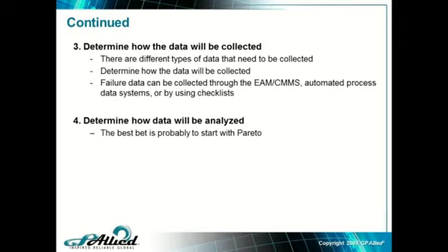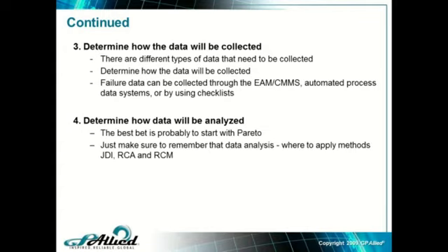And I say the best bet is probably to start with a Pareto analysis. That's the easiest way to start. And just make sure to remember the data analysis, where to apply it, okay? You can just do it, JDI, I call that a JEDI, just do it, you see the problem, solve it. Root cause analysis we may apply, or we may apply reliability centered maintenance to identify what the problem is and what's the solution. What's the correct maintenance strategy we need on this equipment, because evidently it's not right because we're having failures.